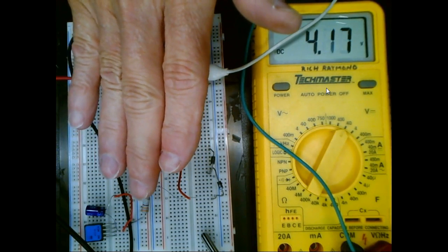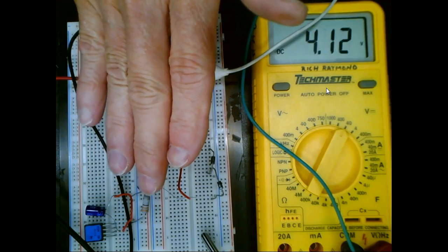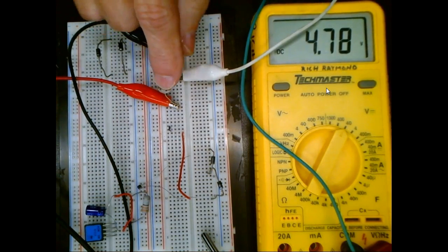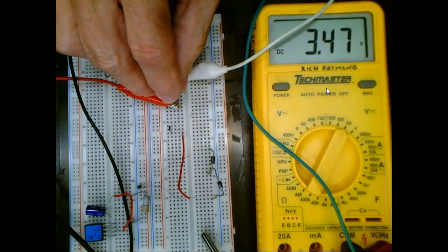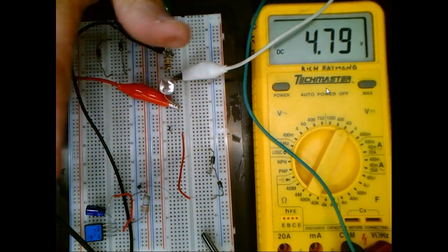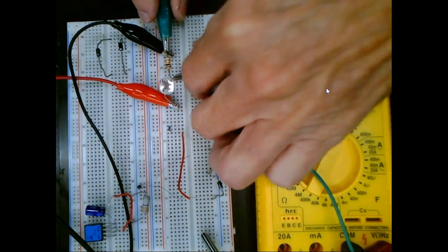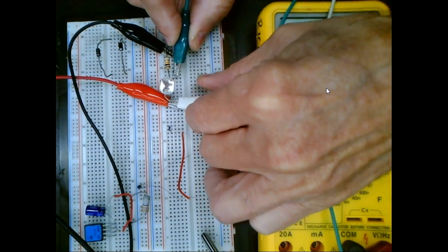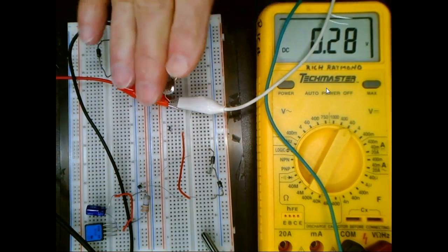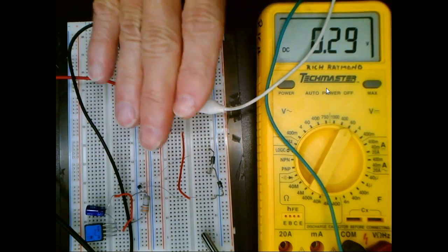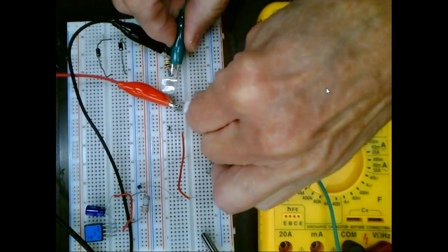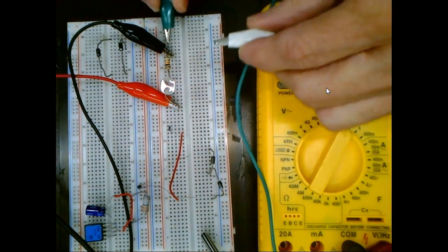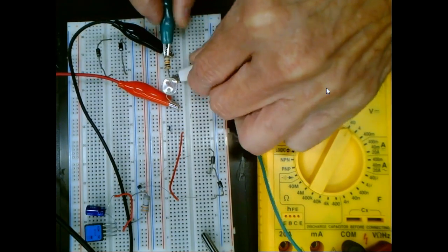so here the voltage drop across my thermistor is doing what? I'm sorry, my photoresistor. Photocell is the commercial name. The technical name is a photoresistor, which is what we'll use here. And of course, it depends on where I take my reference. If I go across the photoresistor, then the voltage will go up, right? So all I did is just change where I took my reference from. I can take it anywhere I want to, right? So here I'm taking my reference across my resistor.